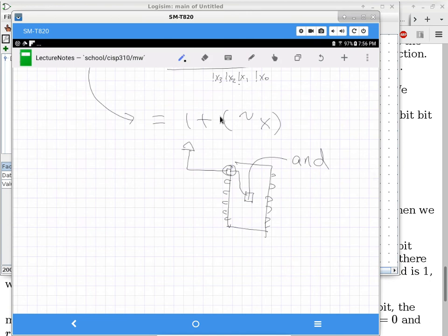This is also a bad idea because if, for whatever reason, this chip is bad, and it is actually trying to drain everything to ground, this is going to be bad for the circuit board. So what you typically do is you use a pull-up resistor like this, and the pull-up resistor can be fairly large. We're talking about 10 kilo ohm or something like that.